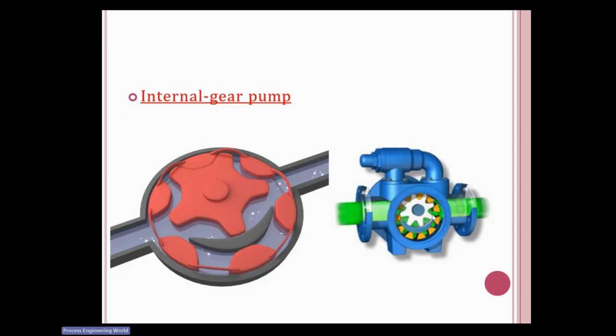Sir, if we have caustic lye solution, and I have two pumps, a centrifugal pump and an AODD pump, and I have to transfer caustic lye solution from the ground floor to the third floor, which pump do I have to use and why? You can use both. See, 48% caustic lye solution, as per the solubility, it is 40% caustic lye solution. But is it homogeneous or heterogeneous? It is homogeneous. So you can transfer it with a centrifugal pump also. You can transfer it with an AODD pump also.